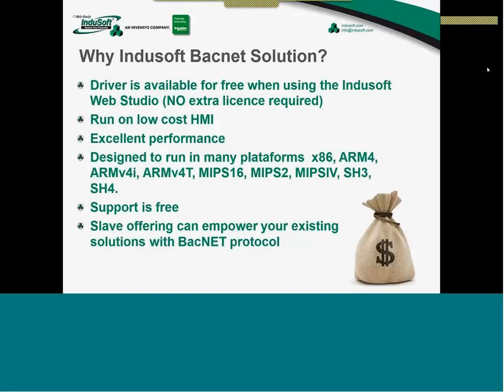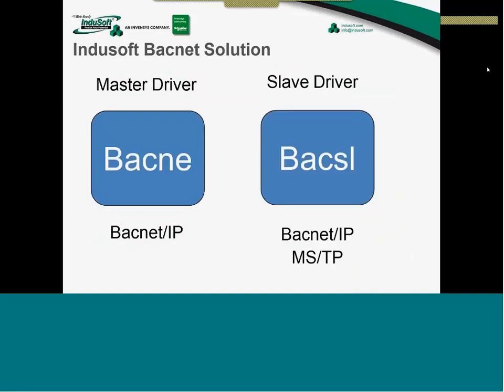So, talking about our drivers, we have a master driver and a slave driver. The master driver supports BACnet IP, and the slave one supports BACnet IP and MSTP. So what's the difference? The master is the software that communicates with the devices, and the slave driver is like a device. So we have both sides.